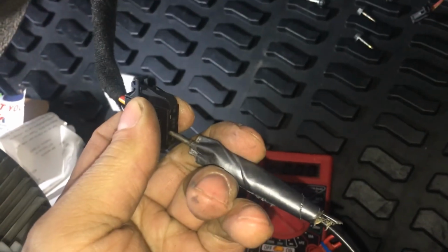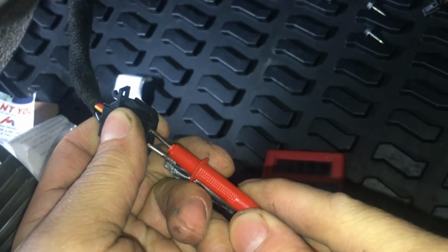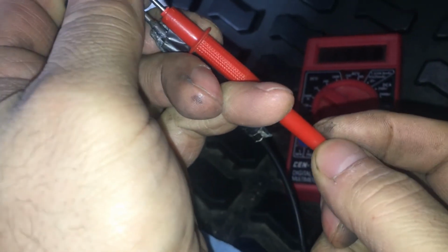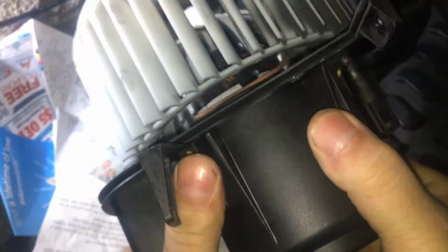And this was turning on and off, like it was not working. I went in through the ECM and oh, well, we got voltage, so this should spin up when I plug it in, unless the resistor is actually in this unit. So let's try to hold on to this thing, turn it strong. It's kind of weird how this is broke. Was that from the factory?